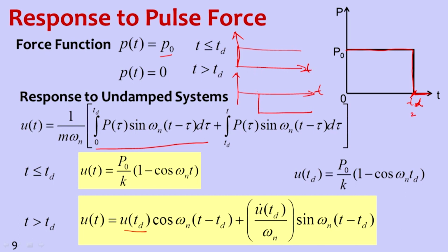So this is Td. What this gives is the constant impulse value. So P naught, a step force, gives the response due to a step force from time t equal to 0 continuously up to any point of time, and this function gives the response to a step force starting from time Td. If we subtract this from the first one, we also get the same value.